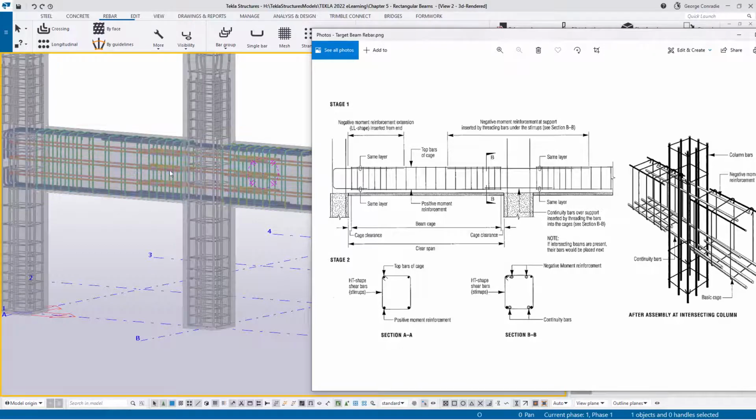And then for our distribution steel, which is not shown in this sketch, we've got the same lapping. And then for our stirrup spacing, we've got close over this joint, which is those. We've got our intermediate spacing, which is these here. And then we've got our short spacing, half spacings on this one again. So we've pretty much